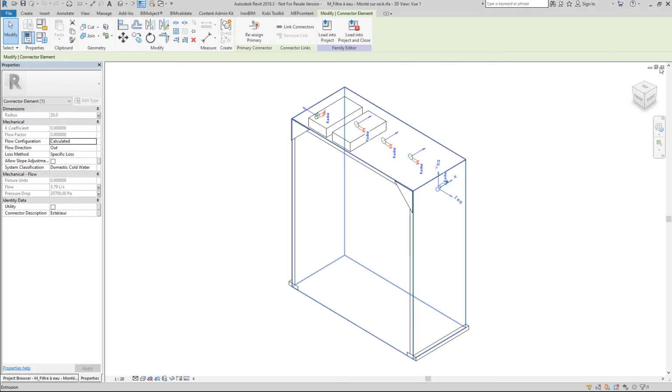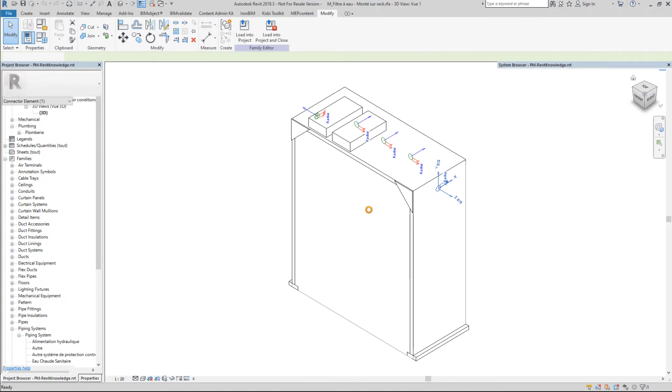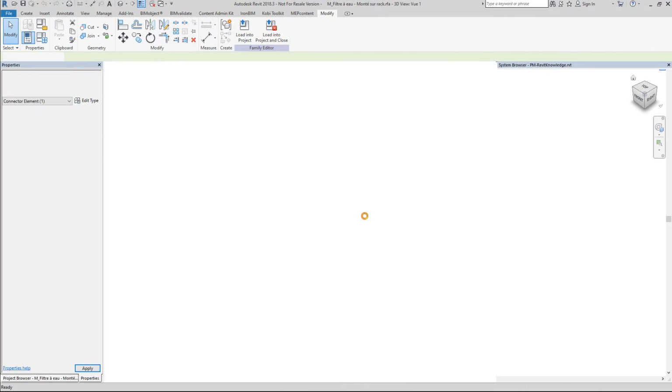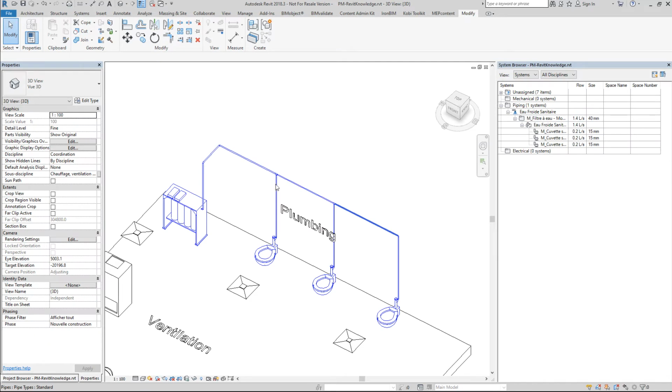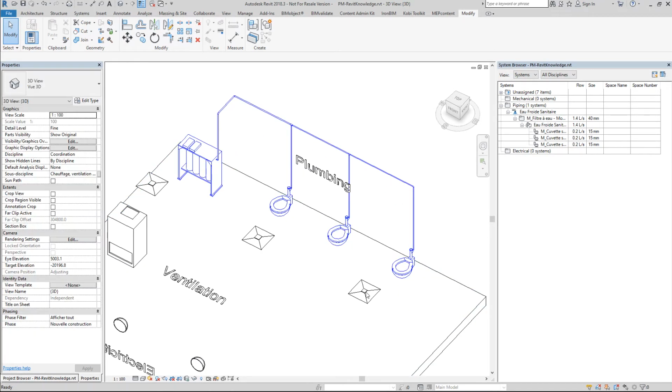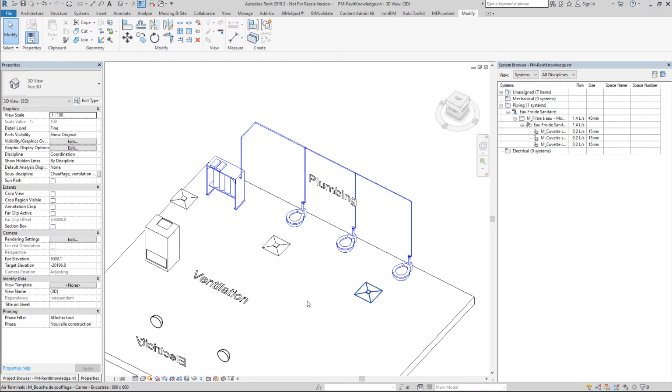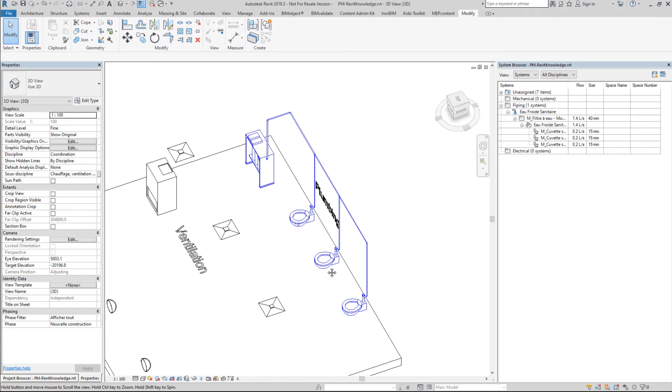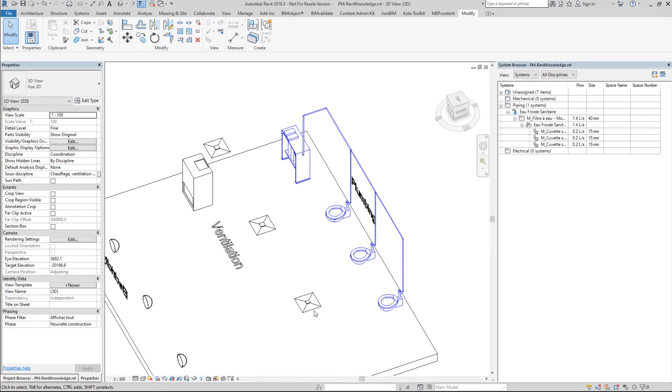So really, that's why you have connectors as presets, and you should really try to have them that way. Sometimes developers forget about it. So if you want some quality in your plumbing fixture, then try to remember this. So now we will go look at ducts, and it's quite similar to piping, to be honest.